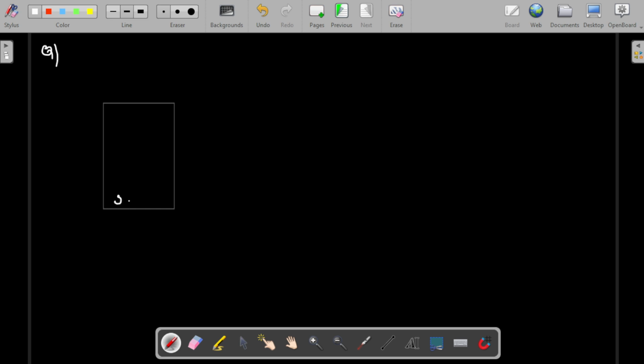Here we are selecting selection lines S1, S0. Here we are giving two inputs, that is A, B. In the question itself they have given four inputs, which are C, 1, 0 and C bar. So this is a 4:1 MUX. The output is F. They are asking us to find what will be the output.